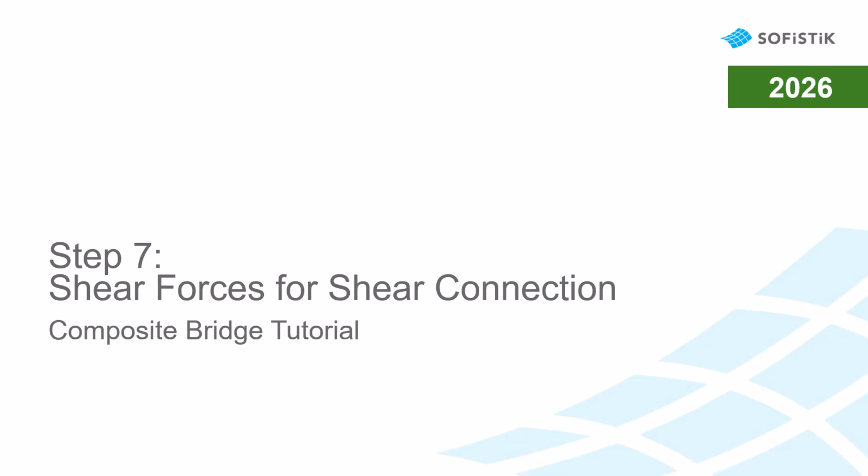In this video of the composite bridge tutorial, we show how to calculate shear forces for the design of the shear connection between structural steel and concrete. According to Eurocode, these shear forces should be calculated using the properties of the uncracked section, even in areas where the concrete acts in tension.